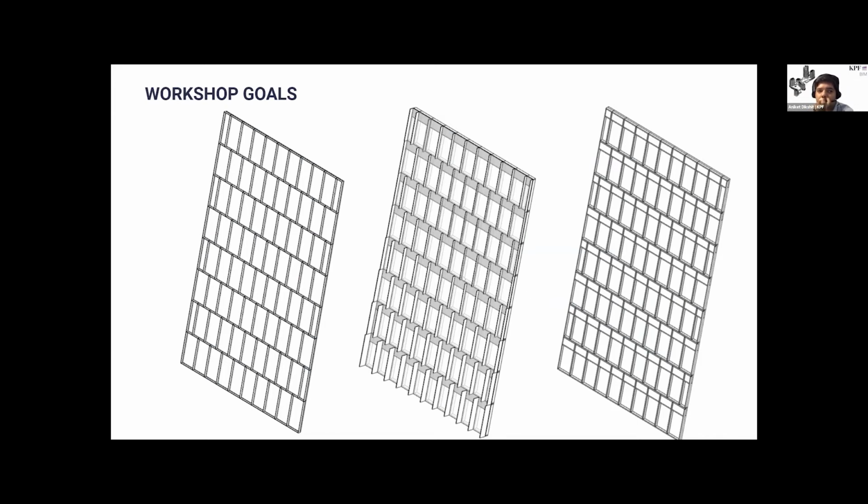So the second one is more a transom panel with a fin. And as you can see, all the fins are unique in a manner. That information was created using an attractor point, and we're going to get into a much deeper end of that as we move on with the workshop. And the last is an 8-point panel, which we'll get into in more depth as well.